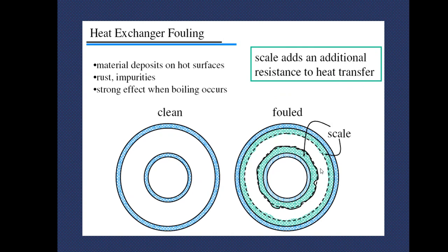So the resistance to heat transfer that before you considered is only on the inner part of the tube, on the outer part of the tube, and the conductivity resistance offered by the material between the two fluids. That's the original thing that we account for in terms of the total resistances, as discussed to you in the previous slide. When there is fouling, you have to add the resistances caused by fouling. And these are the fouling matters here that are already deposited in the tube.